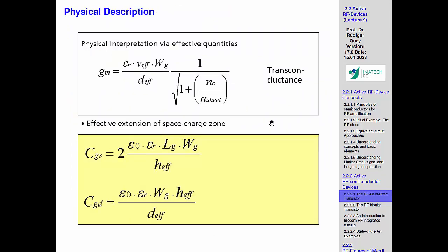Now we also sometimes look at what we can do to improve things. This is also very generic, so you can easily look at that. The first thing is this transconductance, which we are dreaming of to be high. There's a couple of items which we can use. There's the gate width.